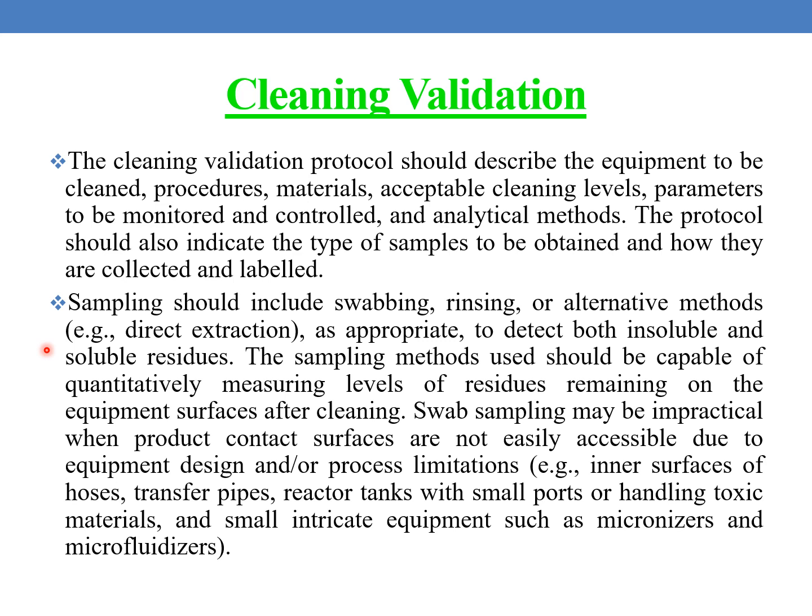Sampling methods used should be capable of quantitatively measuring levels of residues remaining on the equipment surfaces after cleaning. Swab cleaning may be impractical when product contact surfaces are not easily accessible due to equipment design or process limitations. For example, inner surfaces of hoses, transfer pipes, reactor tanks with small ports, or when handling toxic materials, and small intricate equipment such as micronizers or microfluidizers.